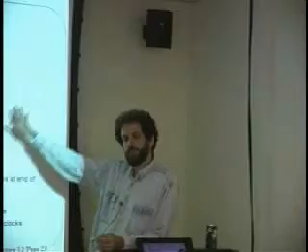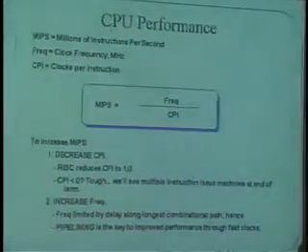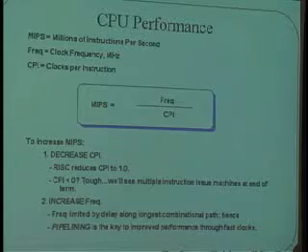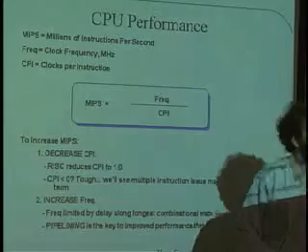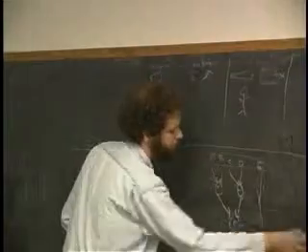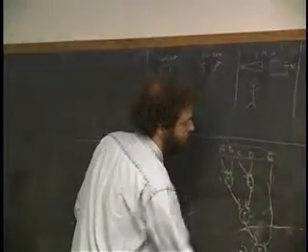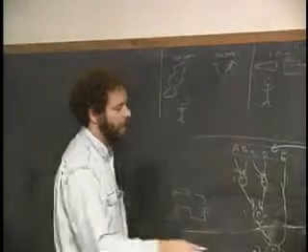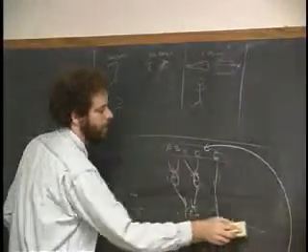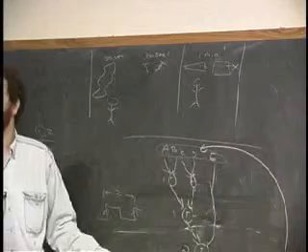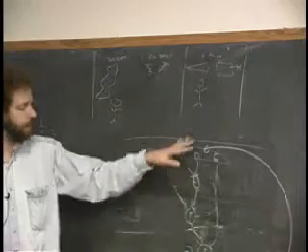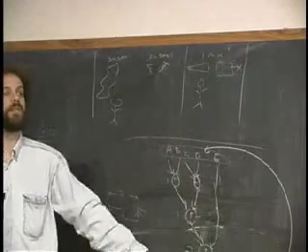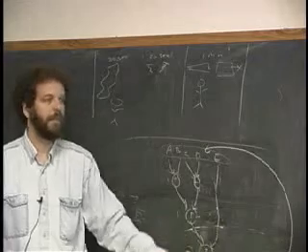But if the combinational delays are too long, then pipelining may be the answer, because it'll cut down the amount of percolation that has to happen in between clock stages. If I ask myself the question, in this circuit over here, if I only have one register, and let's say that there was feedback from the output here back to these data values here, how often can I clock this without another register here? The answer is 1 every 1, 2, 3, 4 clock time units. Okay, because it takes 4 time units for the data to percolate down through the combinational logic that's here till I can clock this a second time.